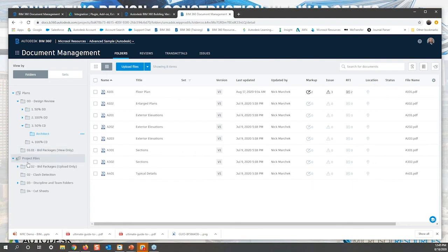And then you could create another folder here under project files for the bid packages themselves, with potentially three subfolders: one for project documents for specs and supporting information, one for pre-bid RFIs, and one for bid submissions. You could then invite all those same prospective bidders to the folder here in bid packages with upload-only permission set, and this setting would carry down throughout all of the subfolders.